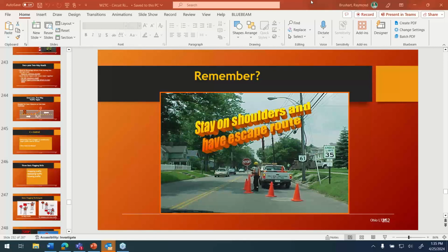So the manual says you are permitted to put traffic signs on utility poles, but when it comes to flagging signs, just rethink that and use engineering judgment on whether the motorist will see them and recognize them.